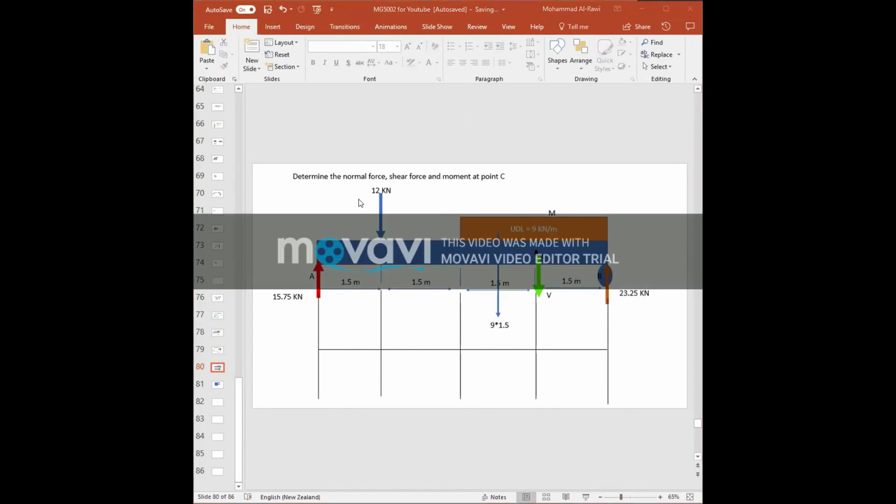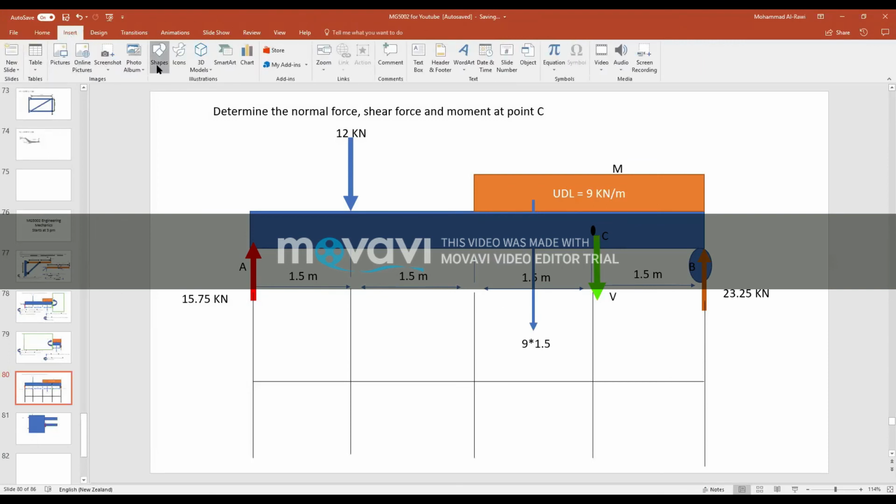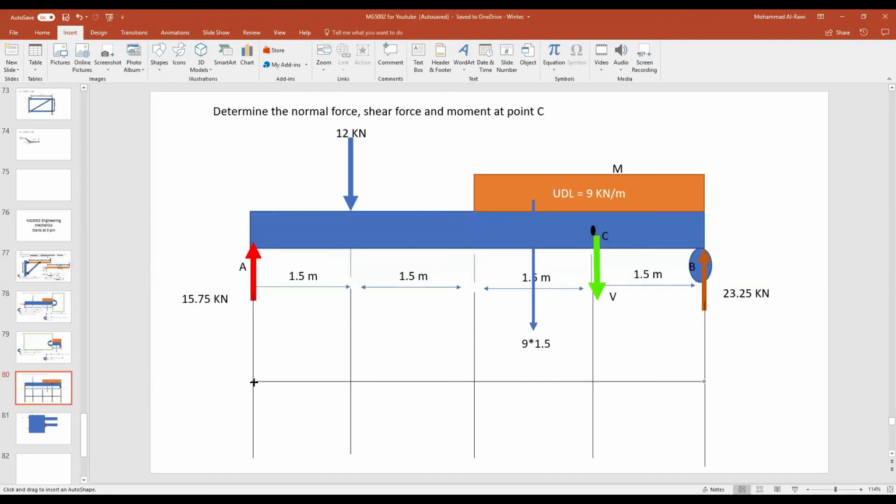All right. Now, what we learned for the shear force diagram: always we start with one of the free ends. I prefer to start from the left, except for the cantilever, where you start from the free end. That's something really very helpful for you guys.